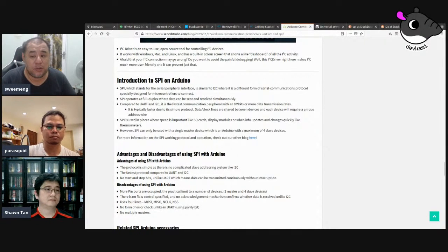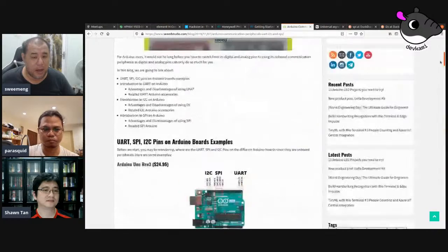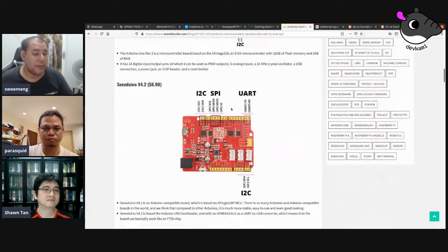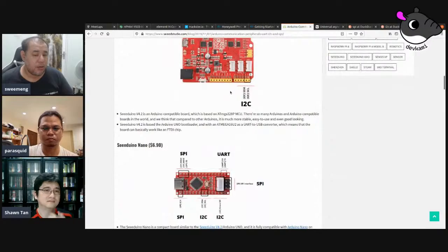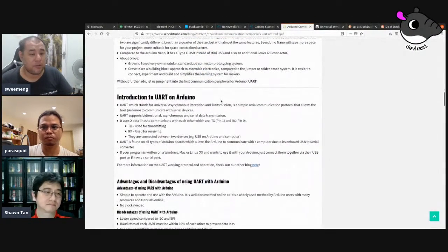And also, let's say you get an Arduino, for example, you realize that you don't actually have that many of those pins. So for example, if you look at the link that I showed you, an Arduino will really have only one SPI, two I2C, and UART. So these things are not free, and it depends on the hardware. For example, I think the ESP actually has more. Everything can be used, but it's something you need to think about.